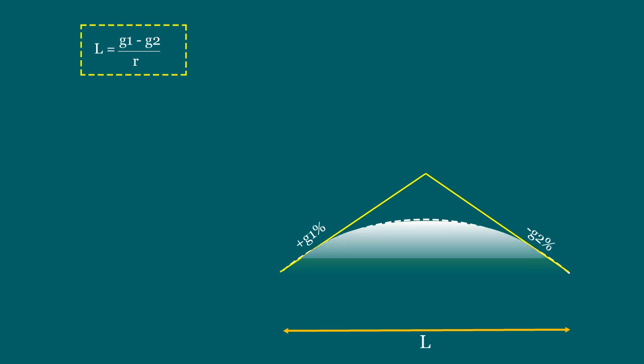Now, we will see what type of curve can be used as vertical curve. Either a circular curve or a parabola may be used as a vertical curve. In a parabola which has a vertical axis, the rate of change of grade is uniform throughout the vertical curve. So, parabolic curves are used as vertical curves. Here, we have to remember our school days and recollect our memories regarding the equation of parabola.